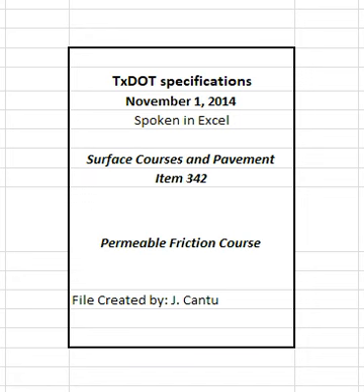Provide the engineer with split samples of the mixtures before the trial batch production, including all additives, except water, and blank samples used to determine the correction factors for the ignition oven used for quality assurance (QA) testing during production. Correction factors established from a previously approved mixture design may be used for the current mixture design if the mixture design and ignition oven are the same as previously used unless otherwise directed.